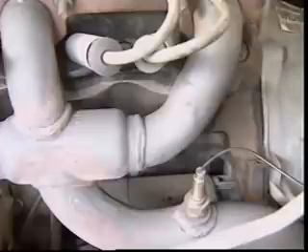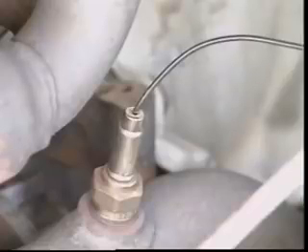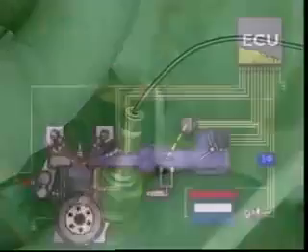One lamp blink, followed by a pause, then 3 blinks in rapid succession, indicates code 13, which may mean, for that application, that the oxygen sensor voltage is not changing, leaving the engine in open-loop operation.